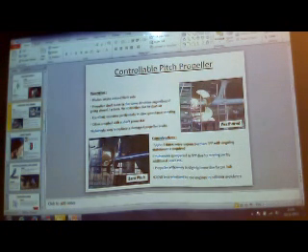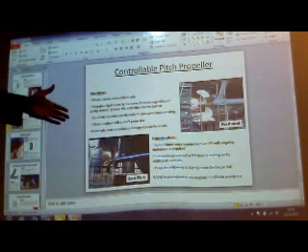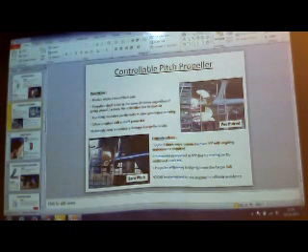If you make the pitch zero, you're just creating a wall behind one of the controllable factors, your rudder, the steering system. You're making it uncontrollable. This is one of the design considerations that you have to bear in mind. So if you're making your pitch zero, you have to be aware of this fact. You will end up not steering the vessel. The vessel might just go wherever it feels like. You are losing the directional stability of the vessel. Get this point? This is one point that you have to bear in mind.